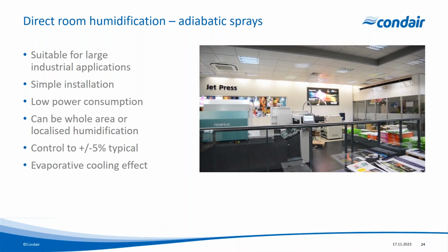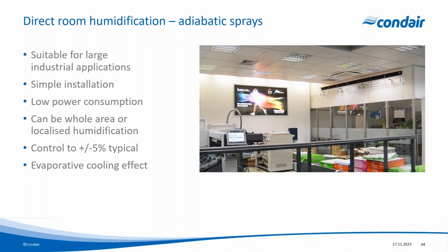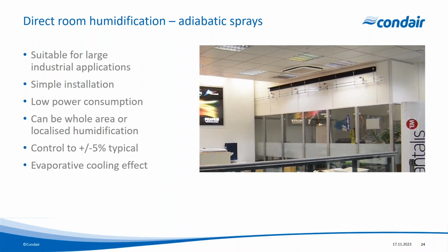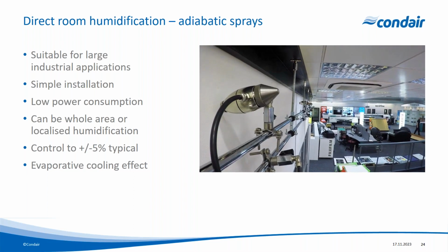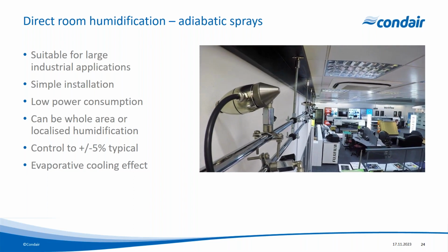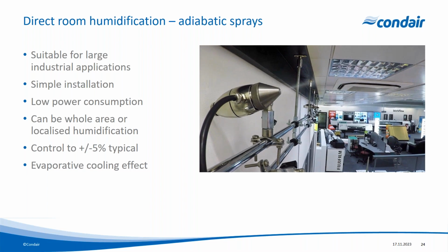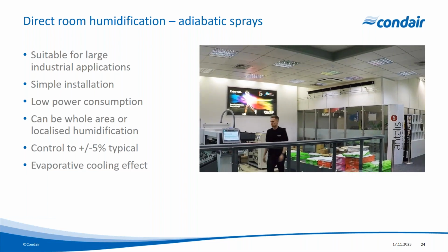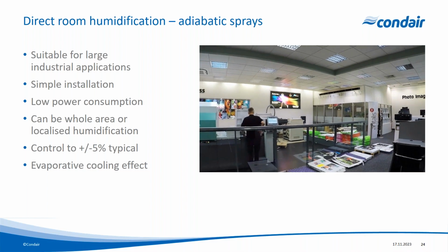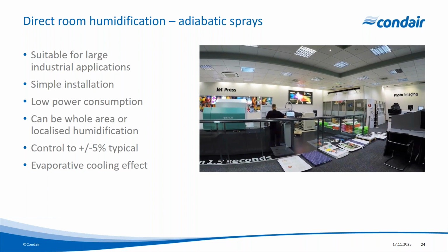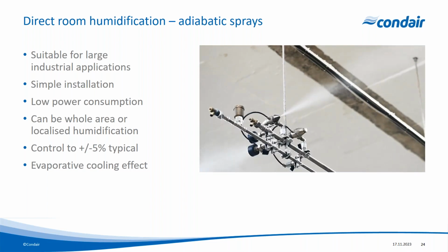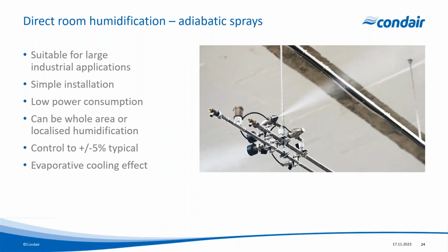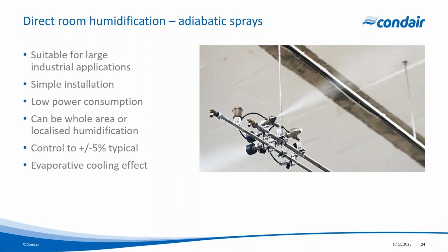So again, they're pretty simple to install, all of these systems. We just need to make sure that all the services are available. They're low power consumption because again, we're using the energy within the heat in the air to evaporate that water. So it's utilizing waste heat. And again, you can do the whole area, or you can just do a localized humidification with different set points in different places.